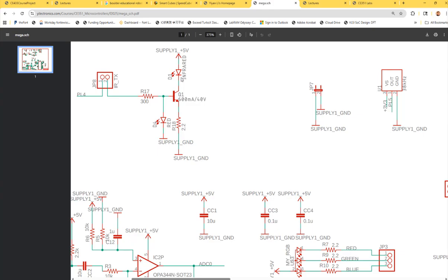So before you do anything else, and you know the pulses are delivered to here, is there any way that you can just detect it, or test it really quick? I would recommend this: you'll know the electrical signals are delivered to the IR LED, but your board is not receiving anything, right? So you can find a different board, like whoever's board, or including my board.